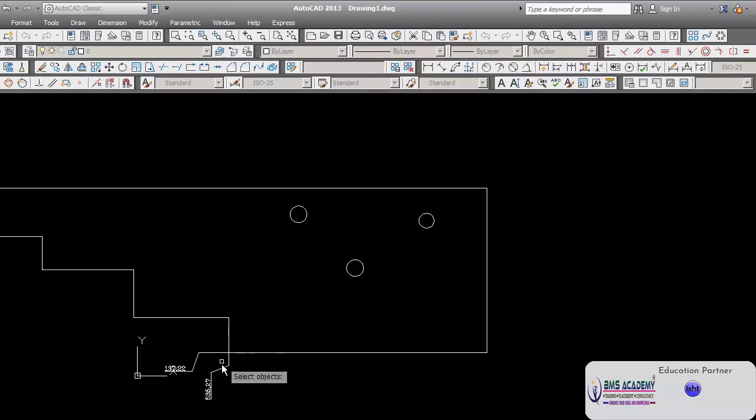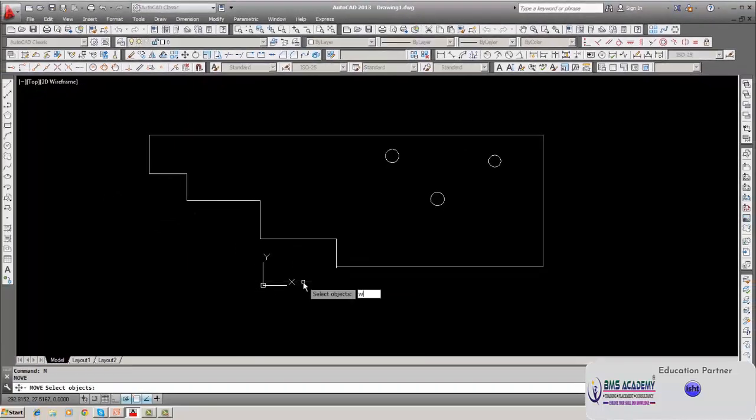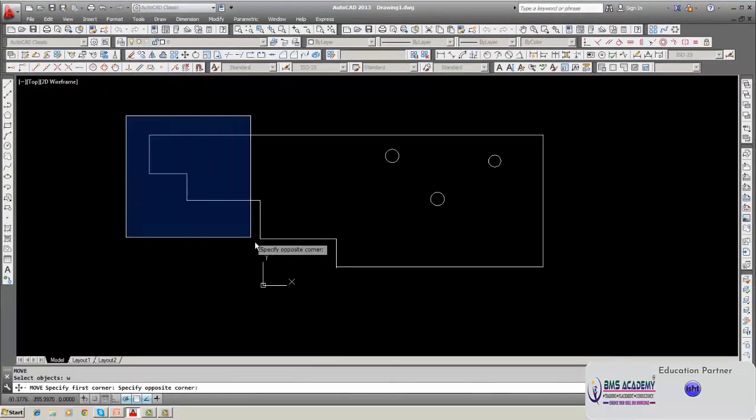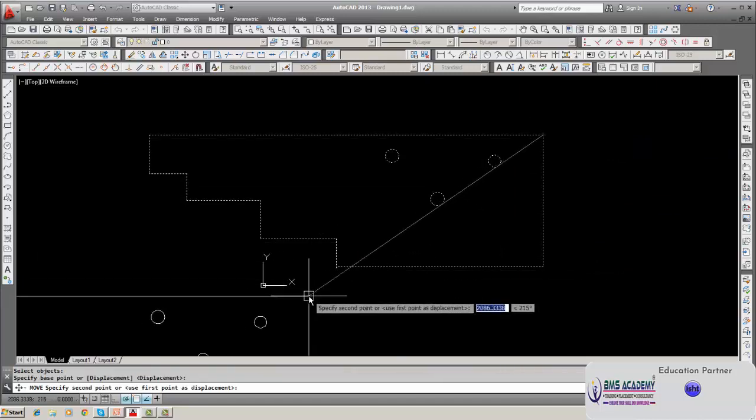You can shift the component to the center line, then you will get it. See, what I do is, I will shift this component, command move. You can shift this entire thing, and suppose you want to take this itself as a datum, shift to 0, 0.